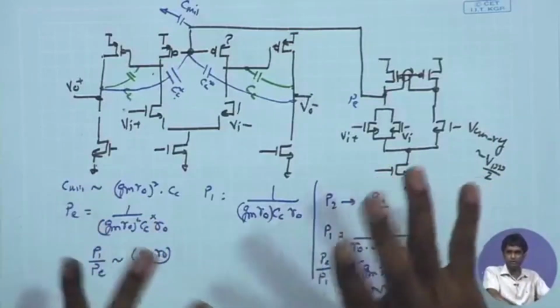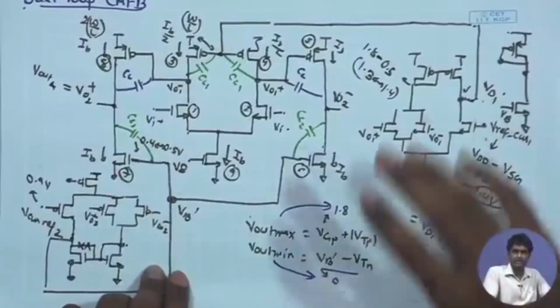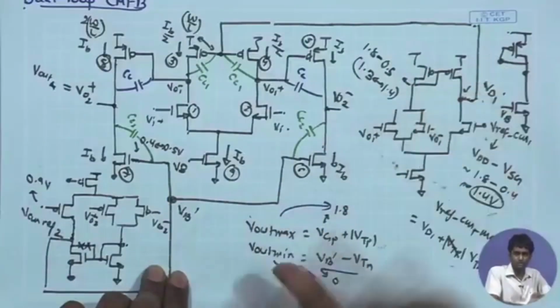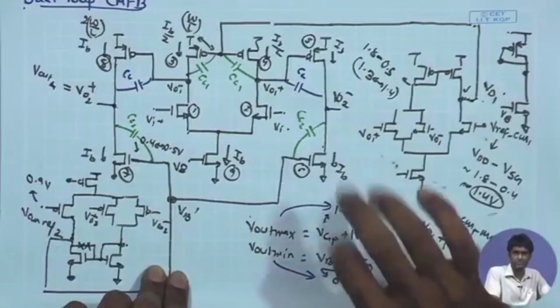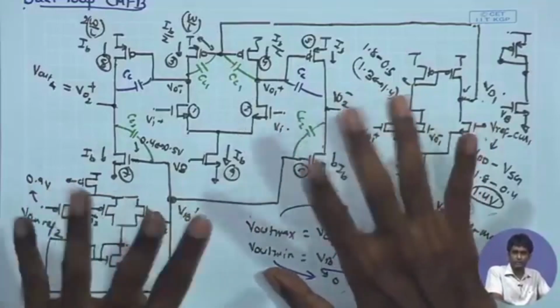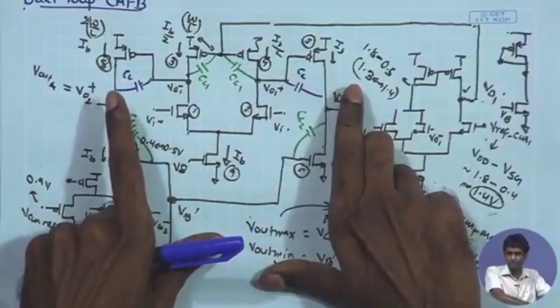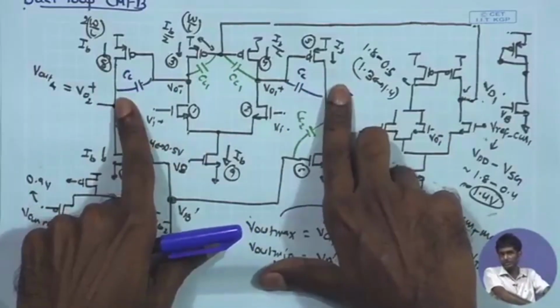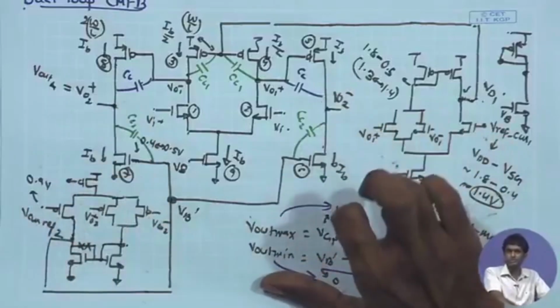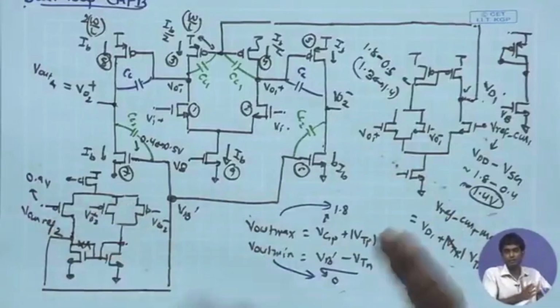The DC biasing point also, you should be aware of the kind of amplifiers to use whenever you are requiring feedback, the kind of topology to use, whether you use a PMOS input device or NMOS input device, what kind of DC biasing to get for references, etc. And then when you are looking at multiple loops, how to look at their interaction, whether the compensation in one loop is interfering with the compensation of the other loop, whether the compensation of common mode feedback is interfering with the differential compensation. Those things are important to be understood, so that you can appreciate what is going on in the simulation, and you can in fact check those effects.